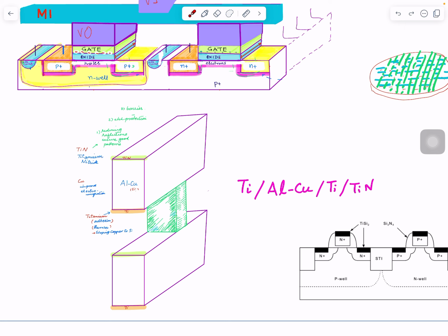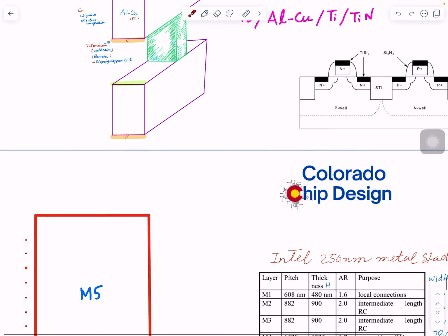Your chip will be in customer hands working 24 hours, 365 days, for so many years, right? Think of those internet boxes that we have, routers. They're always on. So over time, we need to be aware of this for interconnect. What kind of damage can happen because of a lot of current flow, especially in the higher metals that you have seen?